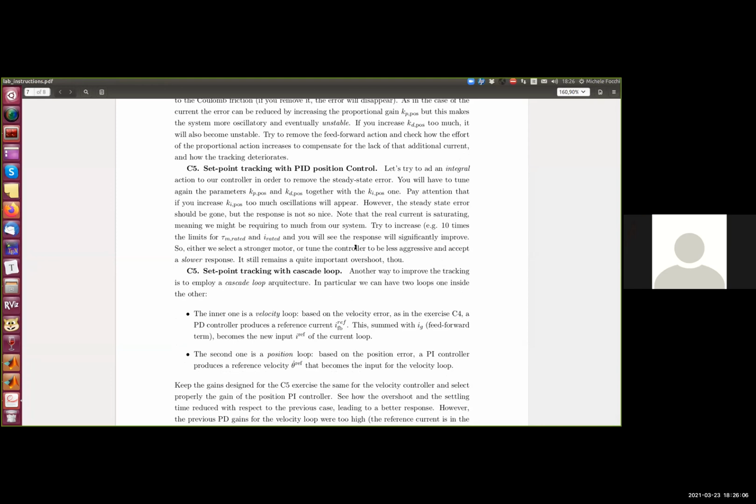I think that we should accelerate to the maximum speed, then keep it, and then decelerate with the maximum deceleration we have. Okay, so the maximum speed, we don't know what it is, but let's say that you can achieve whatever speed. So you could accelerate for the first half of the trajectory at the maximum acceleration, that is, you remember, limited by the maximum torque you can provide from the actuator, and then decelerate at the maximum of your acceleration towards zero. So this will create something at the velocity level, a trapezoidal, triangular shape.